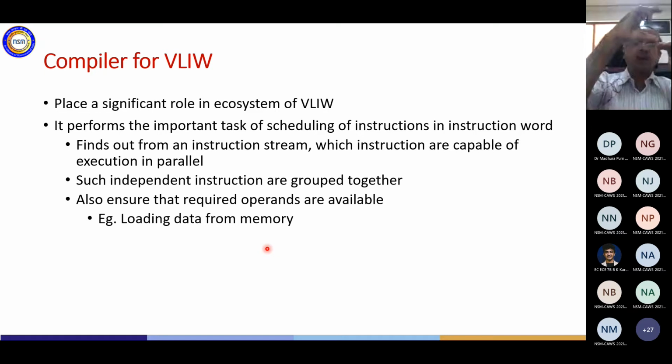It will have to give a gap of 3 instruction words, because those many clocks are required for the data being fetched by this load instruction to actually be there. So what is the compiler doing? It has a stack of serial instructions. It is making multiple piles of that stack and putting them in such a way that there could be some bubbles in between, but making sure that there is no dependency, and when an instruction comes for execution in the CPU, the operand is available.